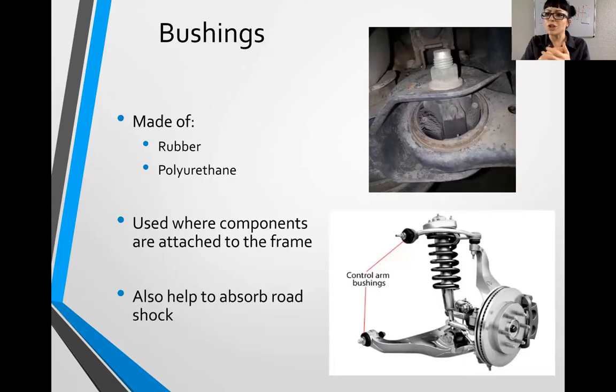So we have sort of a cushion. That's what your bushings are. And when those bushings wear out, they crack, they separate, they dry out. We get a clunking of metal material, and it's kind of like bone on bone, and you feel the clunk inside the car, and you get a clunk sound.